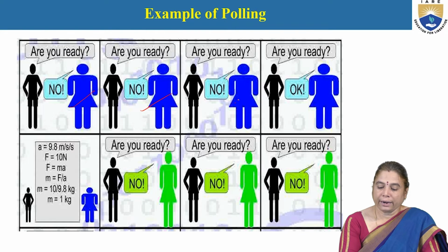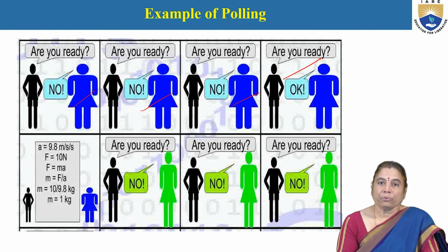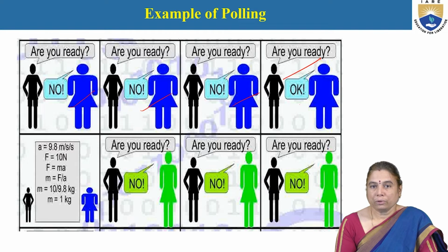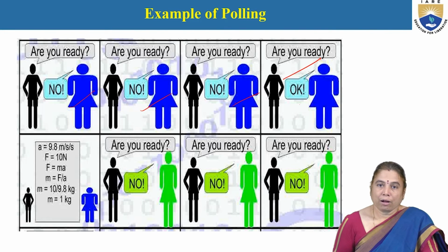Here also not ready. Not ready. Here the device is ready. So this device gains the highest priority and is served first. So with the help of software the polling can be done, and a common branch address can be maintained in the case of polling.